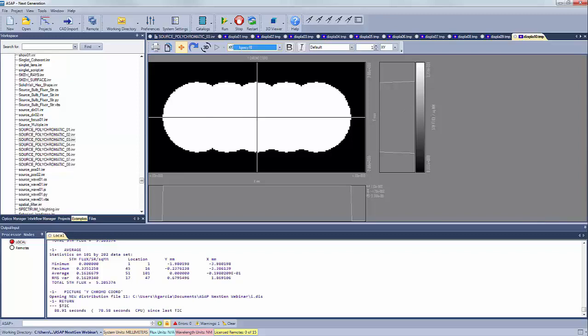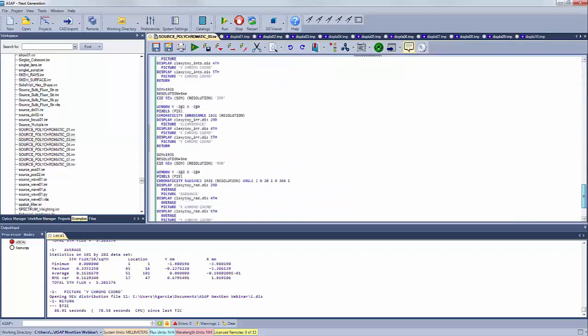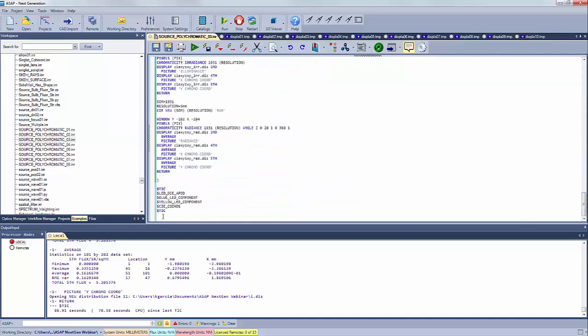In particular in the file, note at the bottom of the file the $tick commands before and after the simulation macro commands. The $tick command computes the overall time since the last $tick command, and it therefore gives an indication of the total elapsed simulation time. As you can see down here, the total elapsed simulation time for 2 cores was on the order of 88.91 seconds.